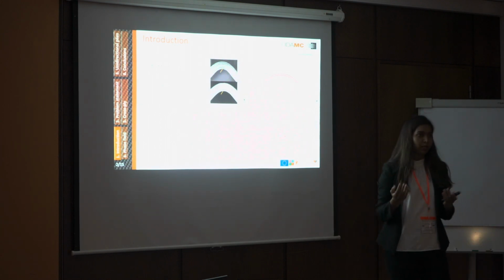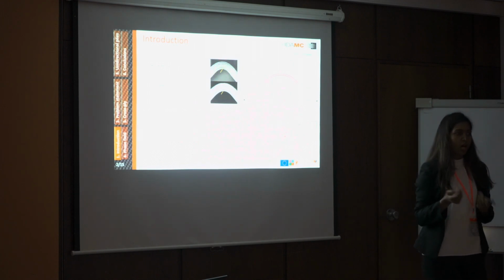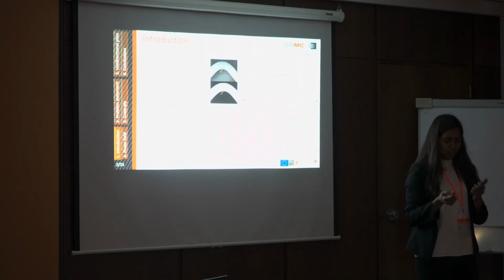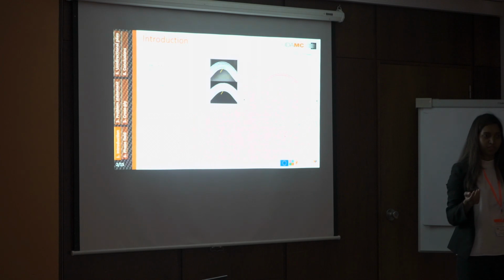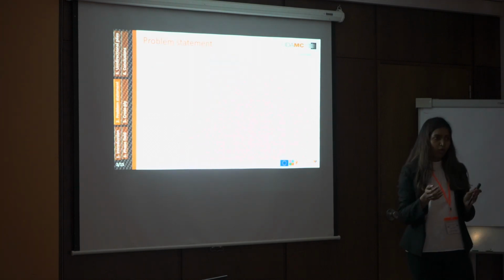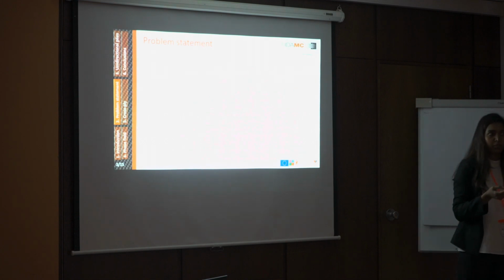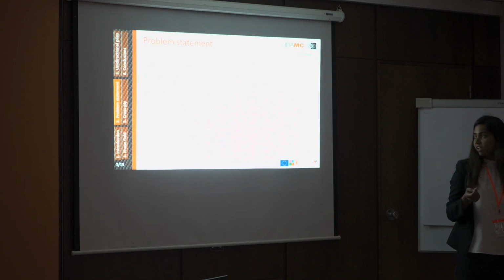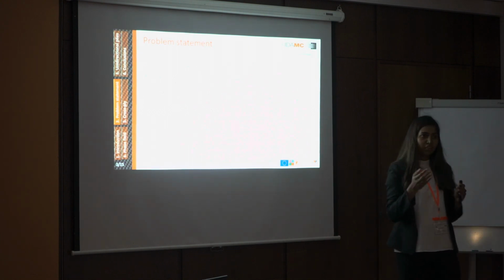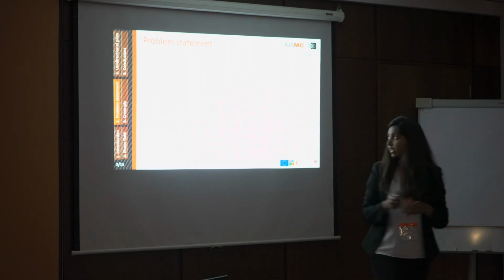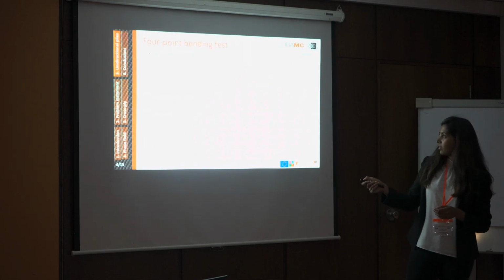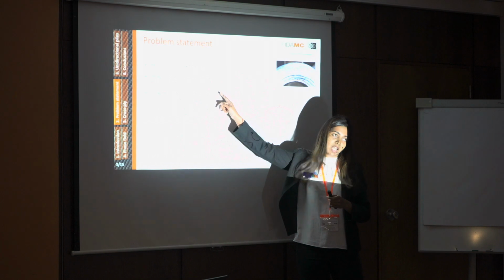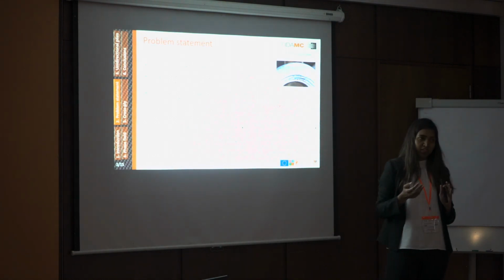These properties are generally obtained by a 4-point bending test, according to ASTM or AITM standards. These standards are designed only for unidirectional curved composite specimens. So when we apply the same 4-point bending test, which is designed for UD specimens, to curved composite specimens with multi-angle plies, it is observed that the damage is initiated because of intralaminar failure, and then it propagates further to form the interlaminar delamination under the presence of high stresses.